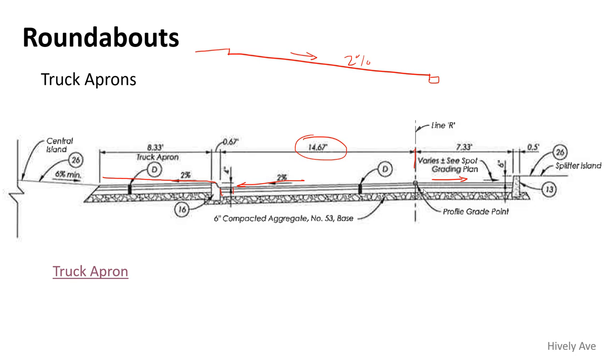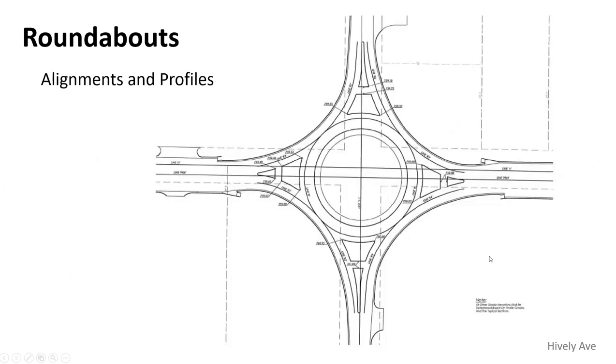That's what our truck apron is for, and even like I say, we could see in that video, really large trucks can handle those, and that's what we designed it for. And this curb, yeah, it's rolled, or it's got a straight slope on the front. It's not that hard on the vehicles if you're going 20 or less, right? And typically a truck is going even less than 20 as it goes through the roundabout. But it's enough of a bump that most passenger car drivers don't want to go through it. And, well, we've got some examples coming up here that maybe some do.